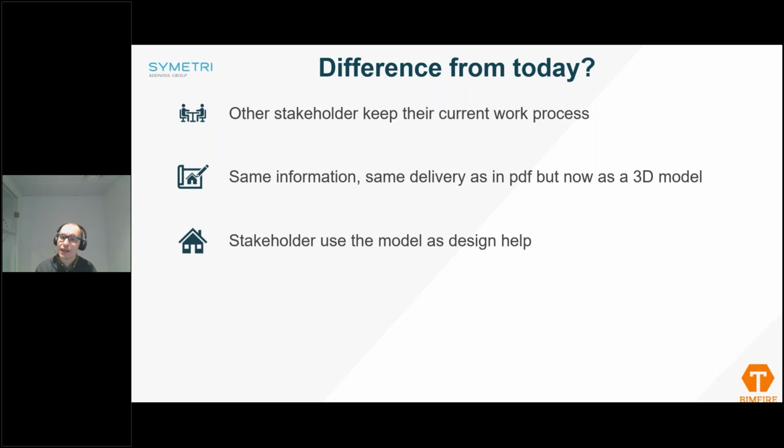Even though we can send data, some information is still good enough as just showcasing on the floor plan. For instance, it could be evacuation routes. We know that that will mean a higher requirement on reaction to fire on those cables and walls. We can showcase that this is 1.2 meters in egress width when we are evacuating, etc. We can still showcase that.